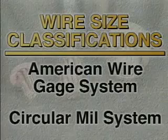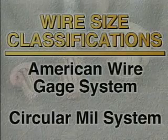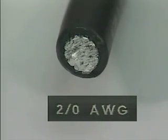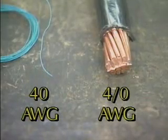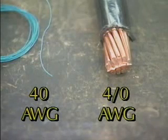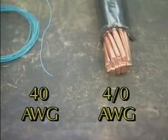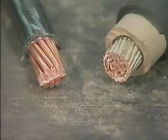There are two systems commonly used to indicate wire size: the American wire gauge system and the circular mill system. The American wire gauge, or AWG system, is most often used to classify wires used in routine electrical work. AWG sizes range from 40 to 4/0, with 40 being the smallest. In this system, the larger the wire, the smaller the number. So 4/0 is the largest wire that can be classified by AWG size.